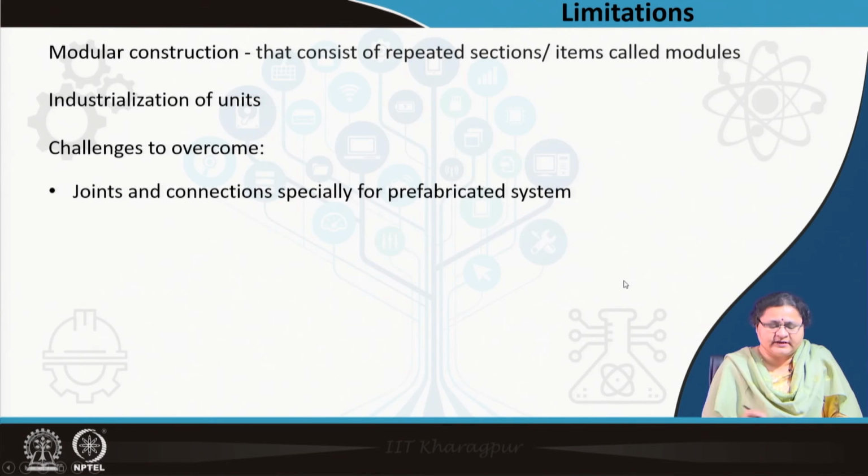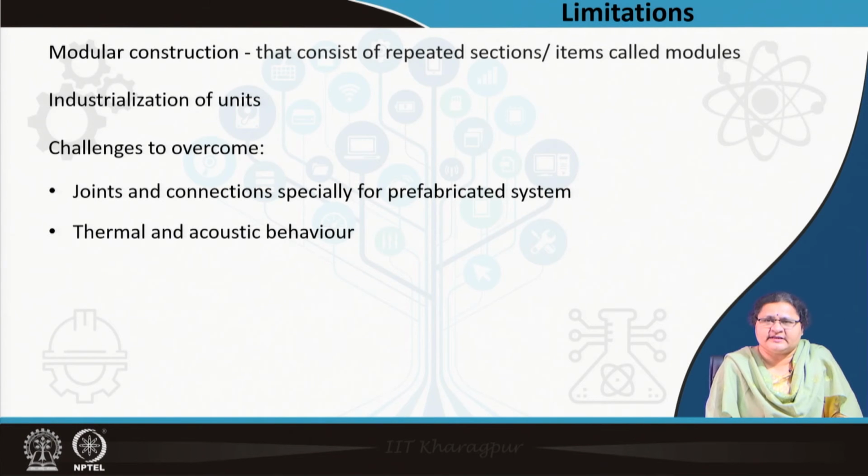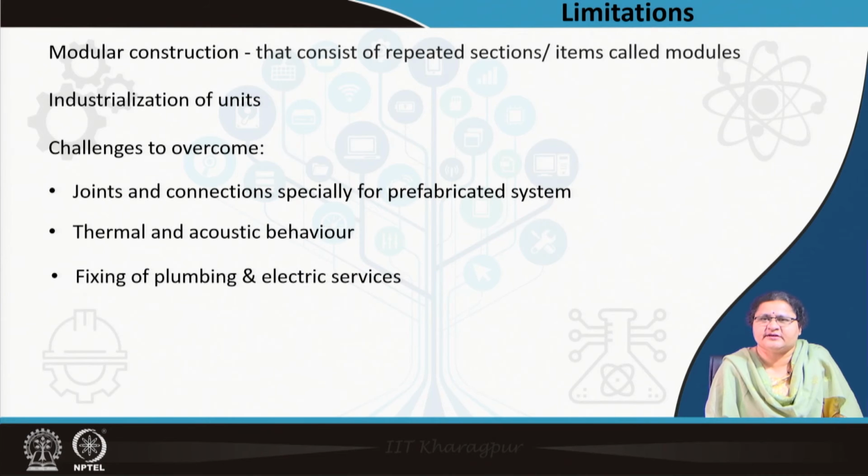Challenges to overcome are the joints and connections, especially for these prefabricated systems. It is not like joining with mortar. There is thermal and acoustical behavior which may be a limitation. You may have problems in fixing the plumbing and electrical services.